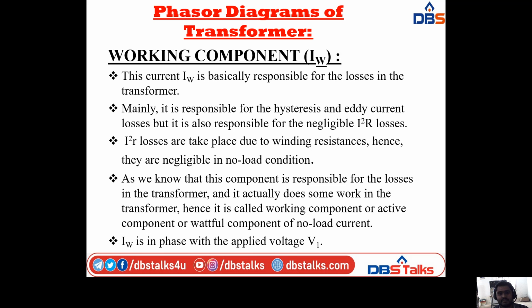Next, coming to the working component. This current, IW, is basically responsible for the losses in the transformer. The previous component, the magnetizing component, is not responsible for the losses, but this working component is. Mainly it is responsible for the hysteresis and eddy current losses.